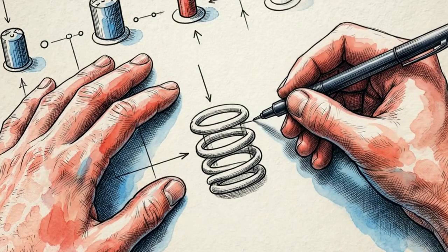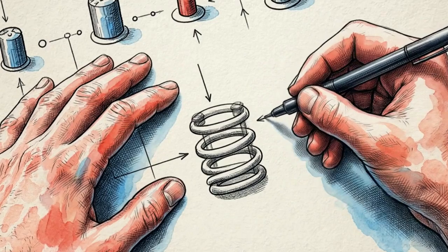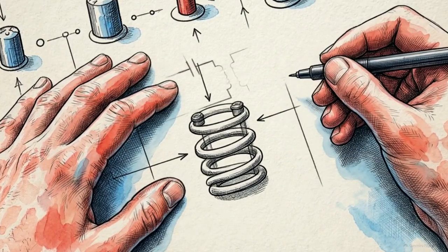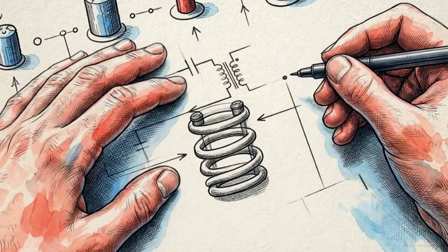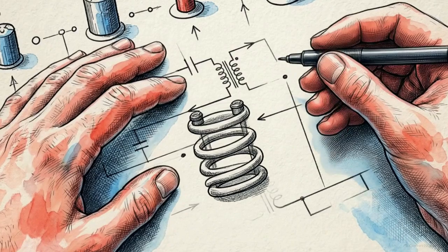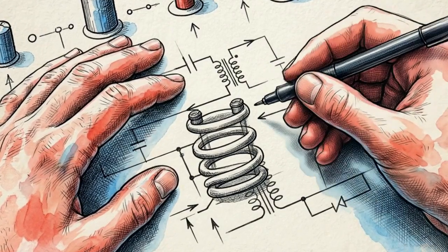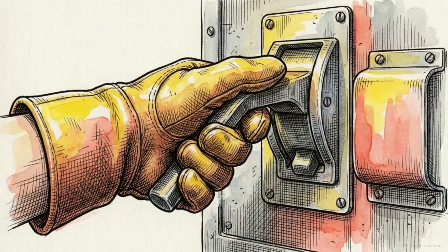Before taking the exam or stepping onto a job site, you need to be able to distinguish between circuit topologies instantly. Here's the core dichotomy. Series circuits run on a single loop, while parallel circuits split into multiple branches. For series, memorize this. The single loop means you have the same current everywhere. For parallel, the shared nodes mean you have the same voltage everywhere.